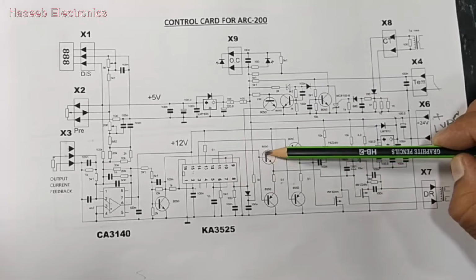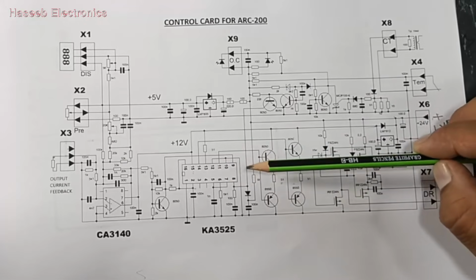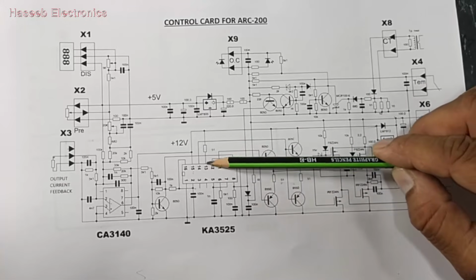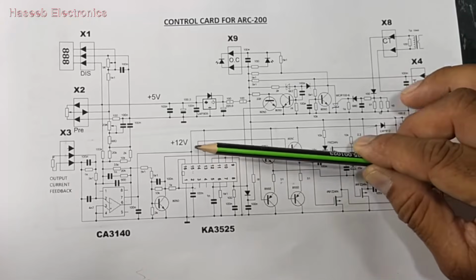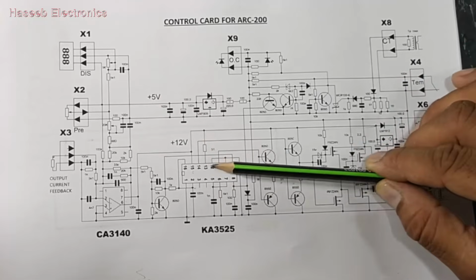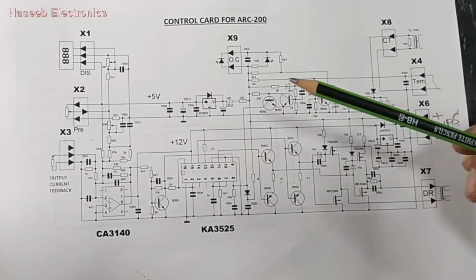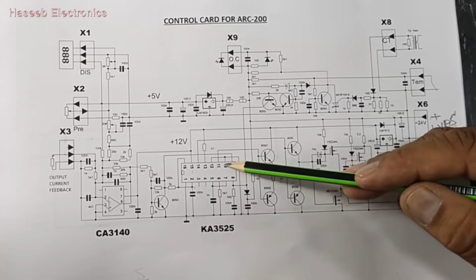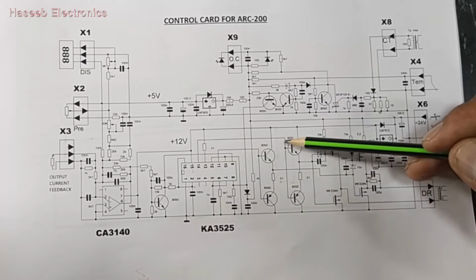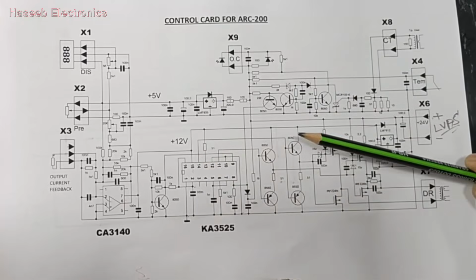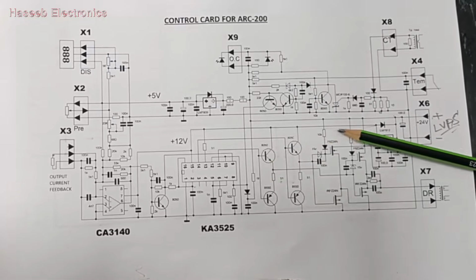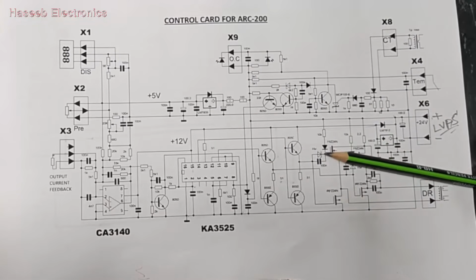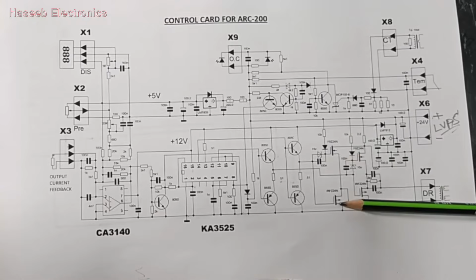Pin 11 is the output pin for channel 1. Pin 12 is ground, pin 13 is VC, the collector voltage for the output switch. Here we have to apply VC voltage and pin 12 is ground, so we will take output from pin number 11 and pin number 14. Here we have the gate drive component for this full bridge switcher. This full bridge switcher is using 4 MOSFETs: 1, 2, 3 and 4.